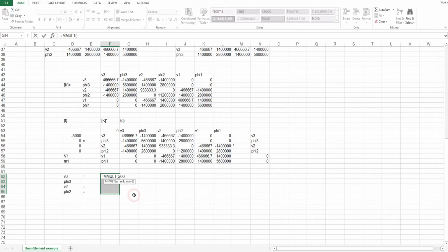So right, maybe I'm a bit hasty at the moment. Okay, so firstly I'm going to divide up the global matrix. You see the last two rows here are going to be 0. That means these two rows or columns are always going to be multiplied by 0, so they become irrelevant. I'm just going to color them pink.